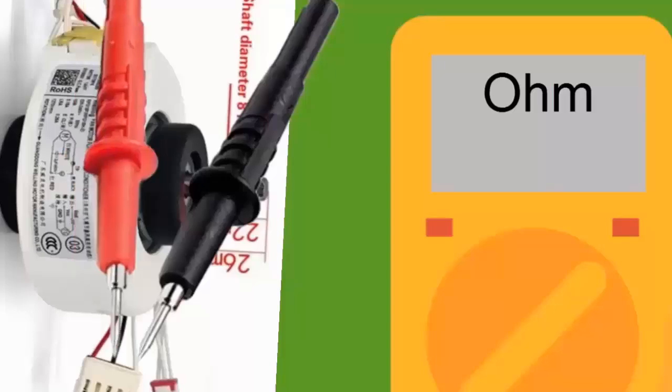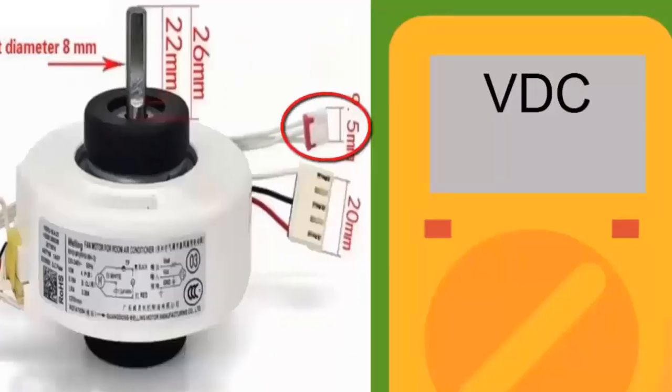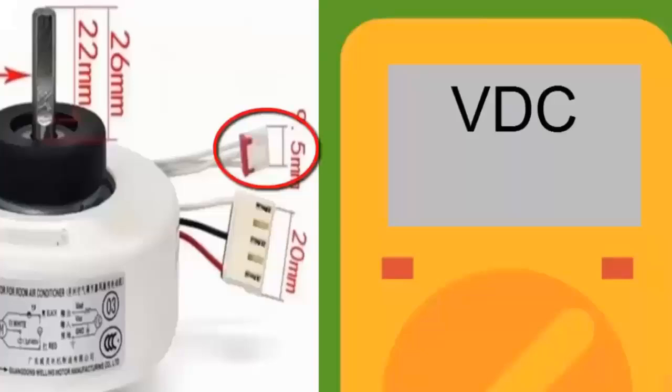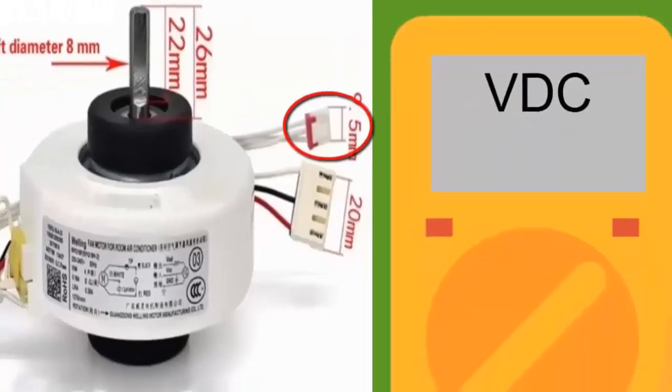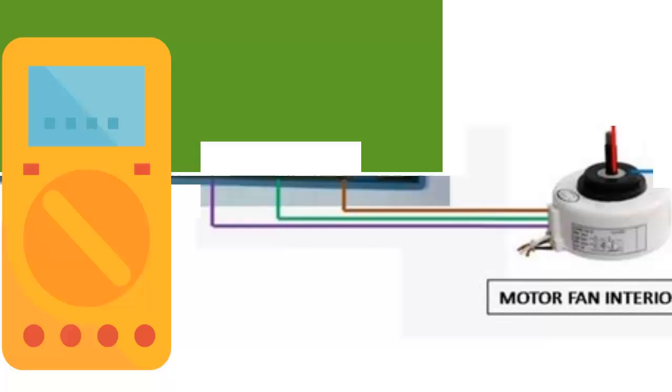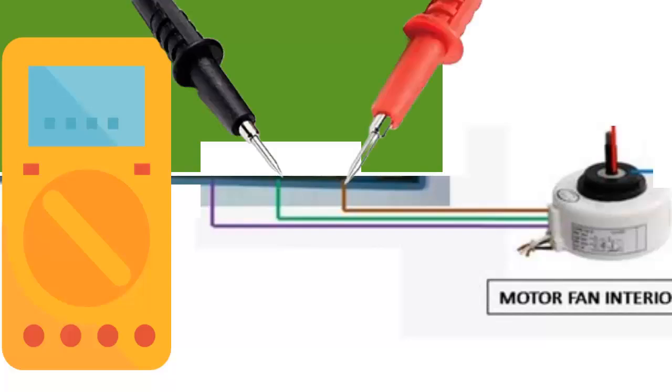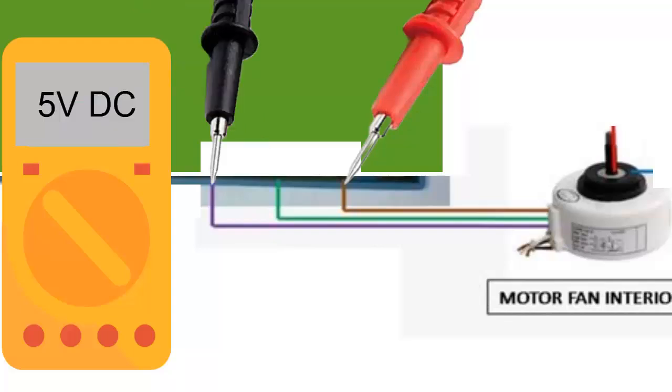8. Check the fan speed sensor signal connector. Identify the 3 thin wires going from the fan to the control board. With the motor off but the thin wires connected and the board powered on, place the multimeter probes on the fan speed sensor connection. When the reading shows 5 volts, the red probe is on the sensor's positive power supply. The black probe is on the sensor's ground. The remaining wire is the signal wire, and this voltage changes when the fan shaft rotates.